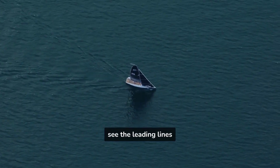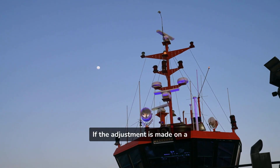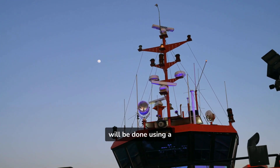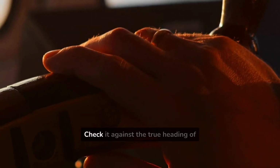H/ If it is a small yacht, see the leading lines available. If the adjustment is made on a merchant ship, it will be done using a gyroscope. In this case, it is essential to verify the gyroscope error. Check it against the true heading of the dock where the ship is moored.